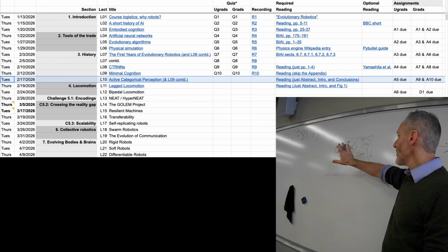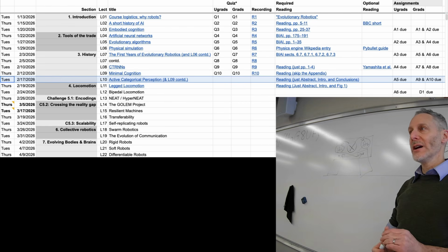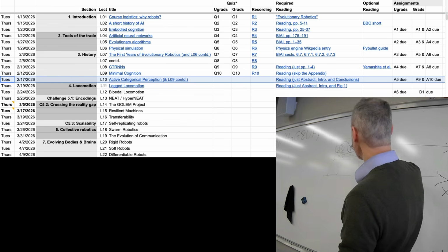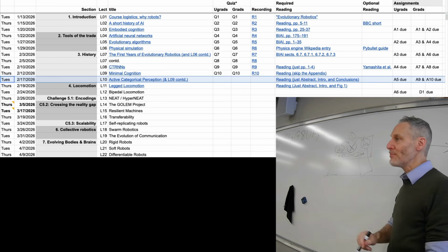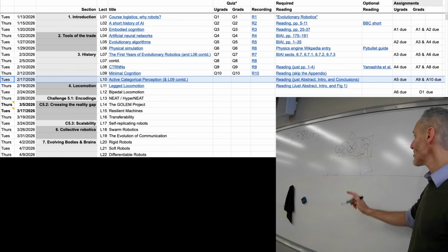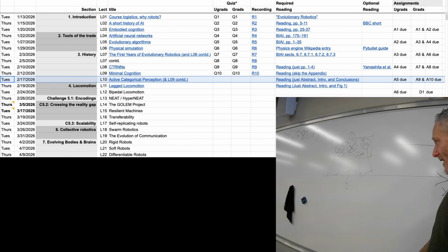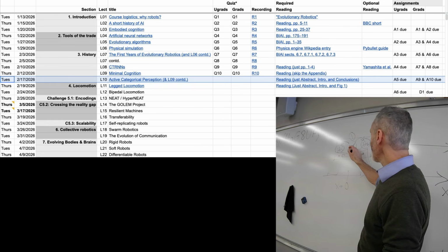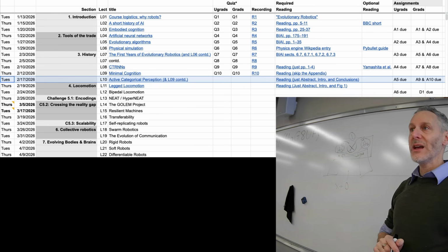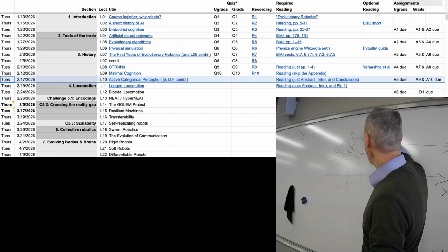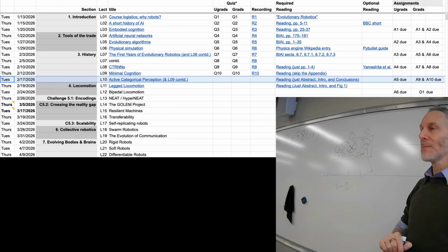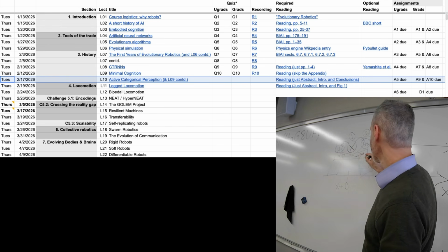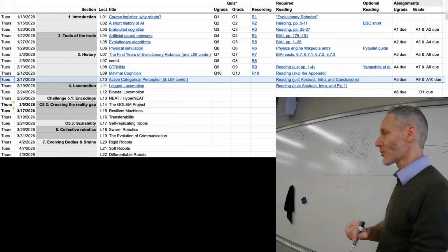Let's imagine this robot operating in a differentiable simulator, which is very much like PyBullet or any other physics engine, in which we're going to start. Step 1, we're going to start by polling the sensor. What is the current value of the sensor? Let's assume the current value of the sensor is at x equals 0. 0 goes in here. The value of the sensor neuron propagates down into the hidden neurons, as we talked about in our discussion of neural networks. And then finally, the values of the hidden neurons propagate down to the motor neurons and ultimately down to the motors that control the joints.